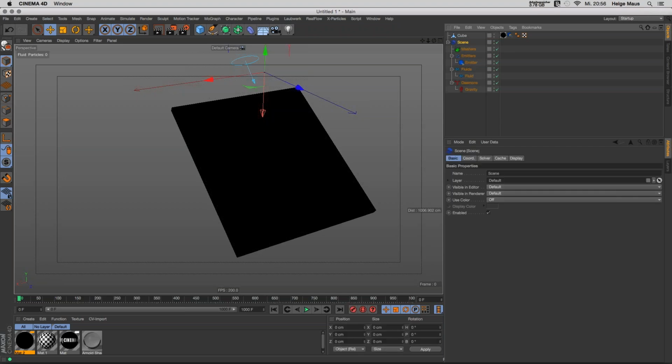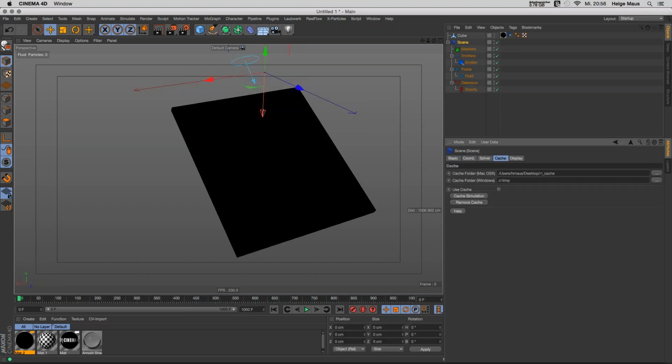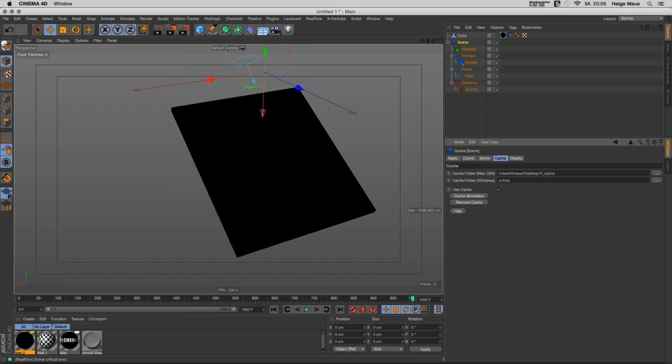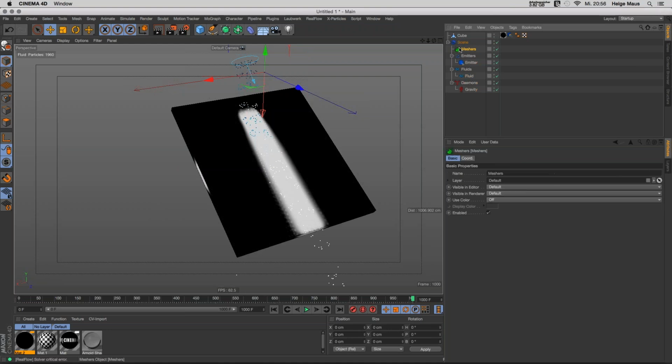In the scene node, you remember we had the caching. Everything we have done can be cached here if you tick here cache. So if you have particles, they are RPC sequences. If you have wet maps, they are PNG sequences, which you can use. Every material you add here with a shader like this adds a PNG sequence with the wet map. And every mesh you generate here is also an Alembic file, an ABC file, so you can use it also in other circumstances. Okay, this is the introduction to this.